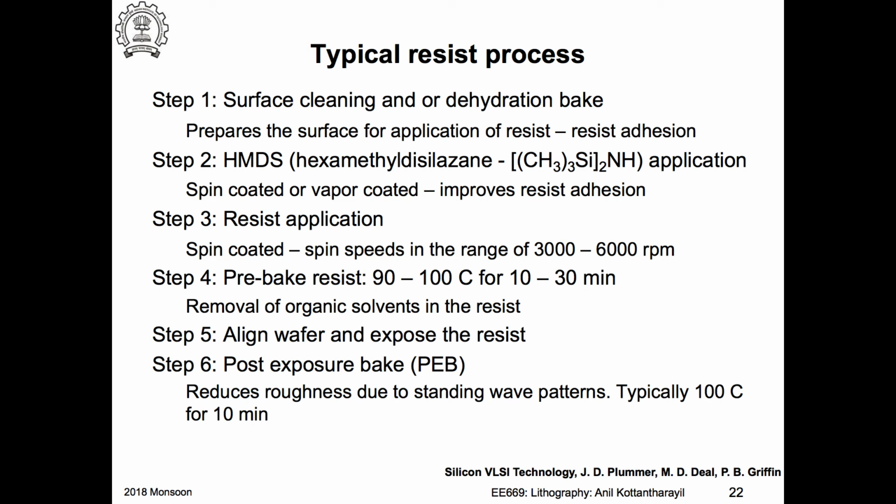So you have the light that is coming in, and if part of the light gets reflected, then you can create standing waves in the photoresist. In that case you may get some strange features, which I'll show you on the next slide. If you do a post exposure bake, the roughness is seen to be reduced. It depends on the photoresist. This is one typical number.